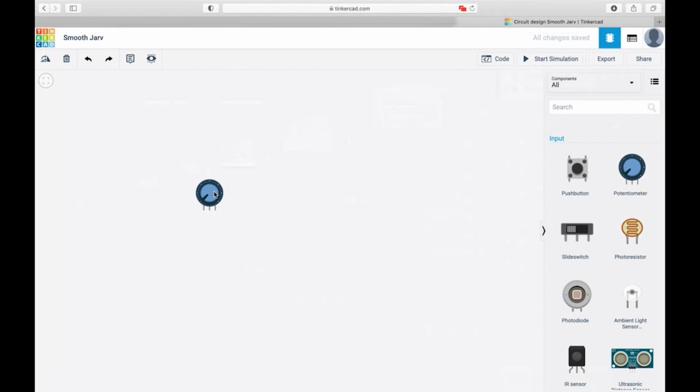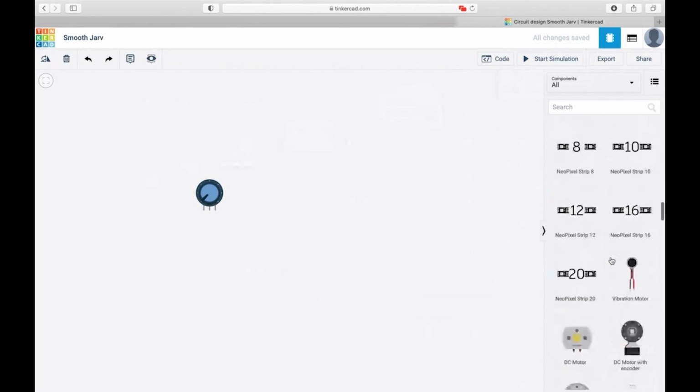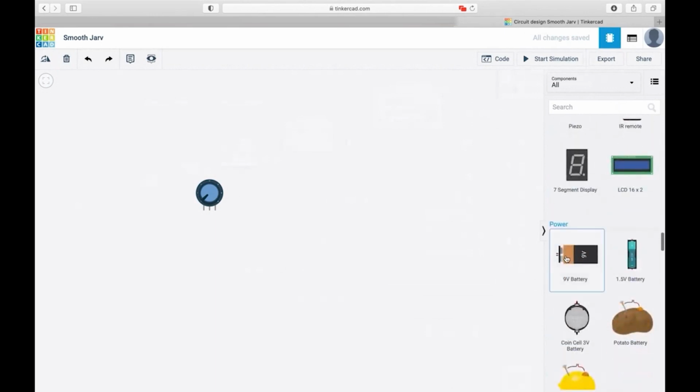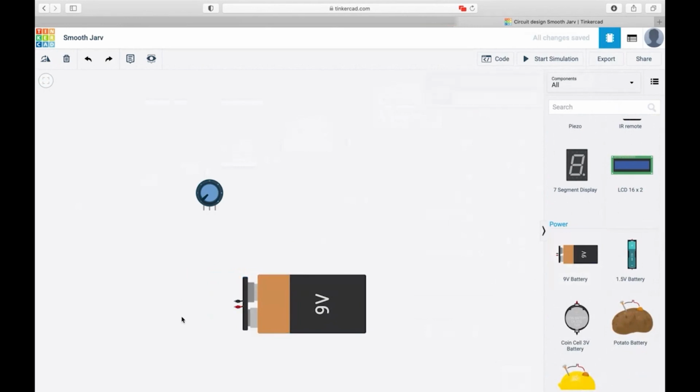In this potentiometer, firstly try to learn what I was talking about in that diagram. You choose a battery, 9 volt. The positive of this battery connect to this terminal. The negative of the battery you connect to this terminal, because these two terminals, I have told you, here we give the input, the positive terminal of the supply, and here we give the negative terminal, that is ground. And this is the wiper where we can have an output.